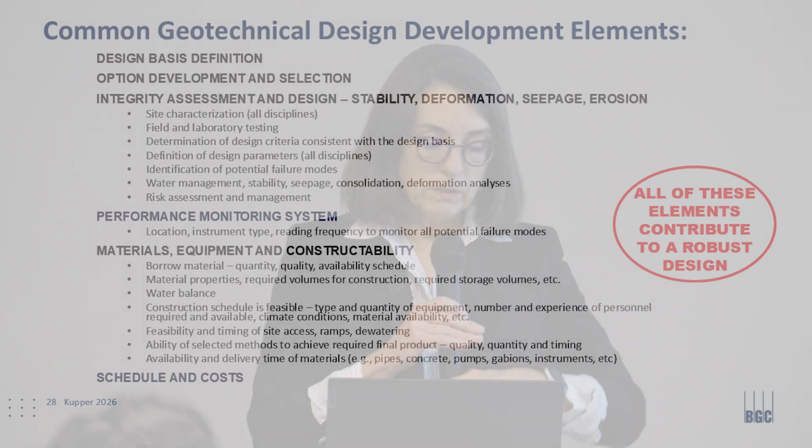So just to wrap up here, I'm going to give a simple example. This is a very common cross-section of a tailings facility in the oil sands. So usually you've got your structural part, which here is the compacted shell in orange. You get the rest of your deposit. You've got your foundation stratigraphy. So for this example, we're going to focus on this thin layer, kind of white or grayish color, that's a clay, say a Pleistocene-aged clay.